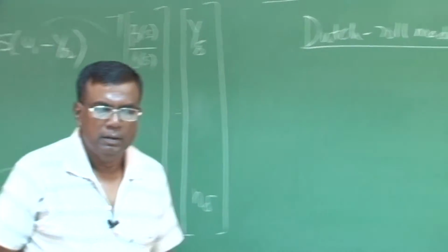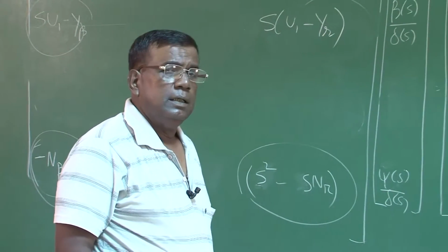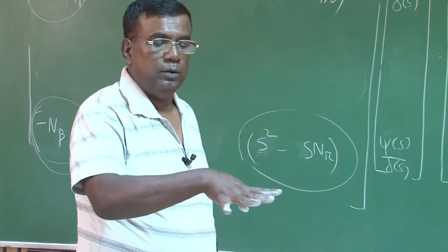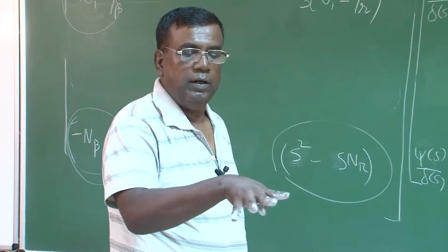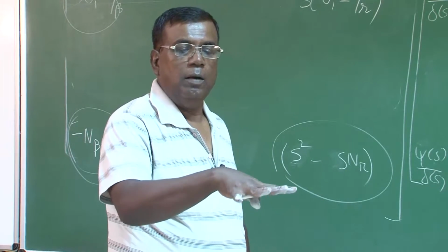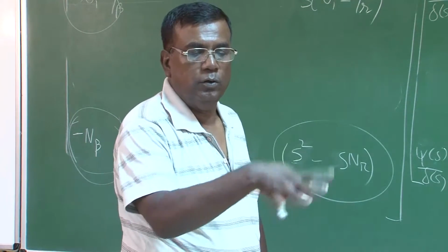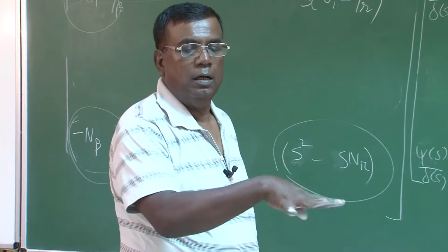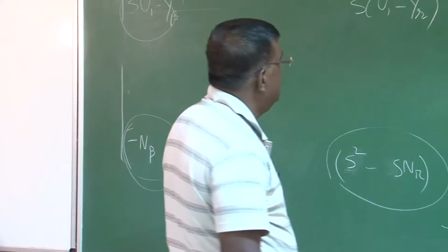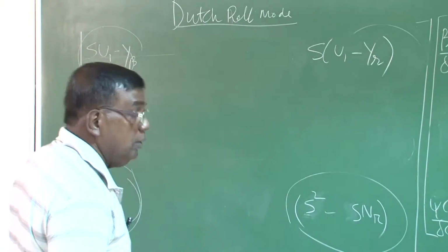Physically, what is it? As we have agreed, the airplane in the lateral directional case can get excited into spiral, roll and Dutch roll. Dutch roll is primarily yawing like this, and also this motion, right? Although there will be some bank disturbances, primarily it is this and this. This is the Dutch roll. So you go like this. Okay, and this is approximated by keeping only this fourth term, with beta and psi, no psi dot.